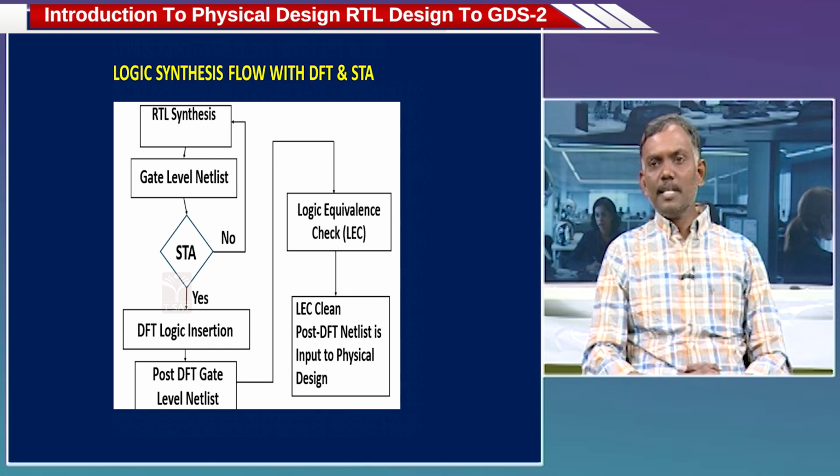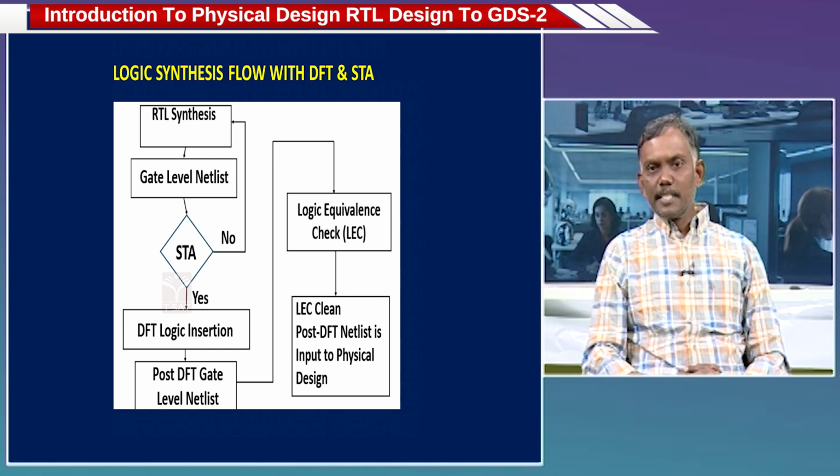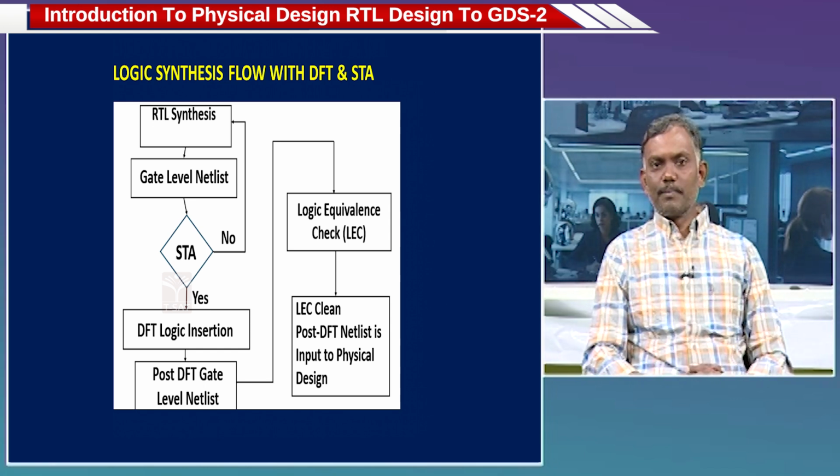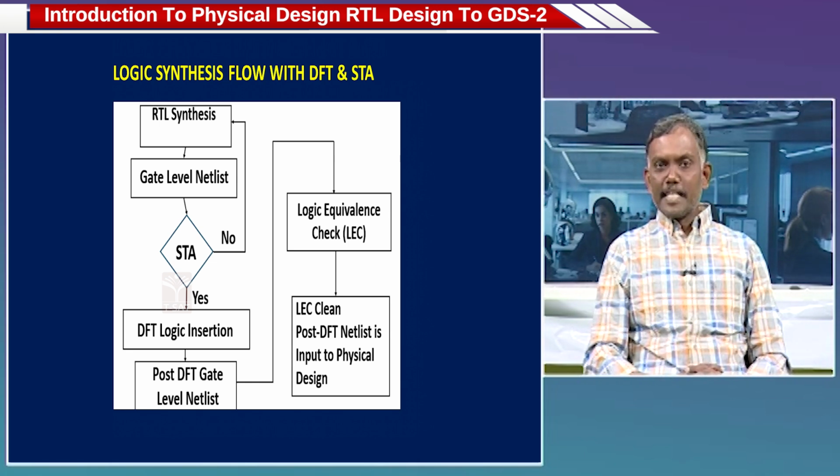That check is called static timing analysis. If the STA is clean, with no violations, then you can go to the next step. If the STA has some violations, as we discussed, we need to do the optimization by rerunning the synthesis or by changing the design. Once STA timing is clean, the next step is the DFT logic insertion.